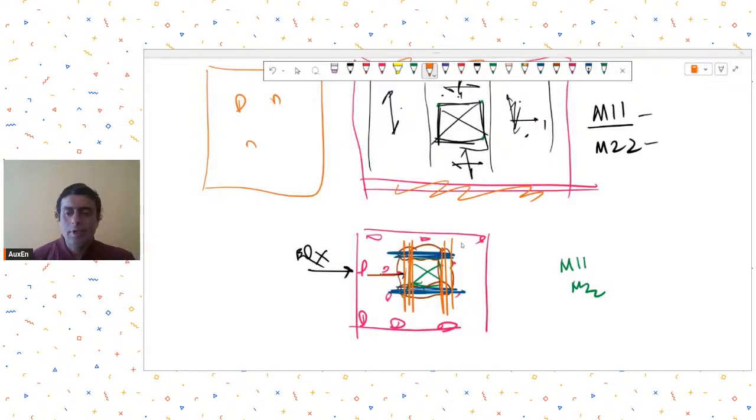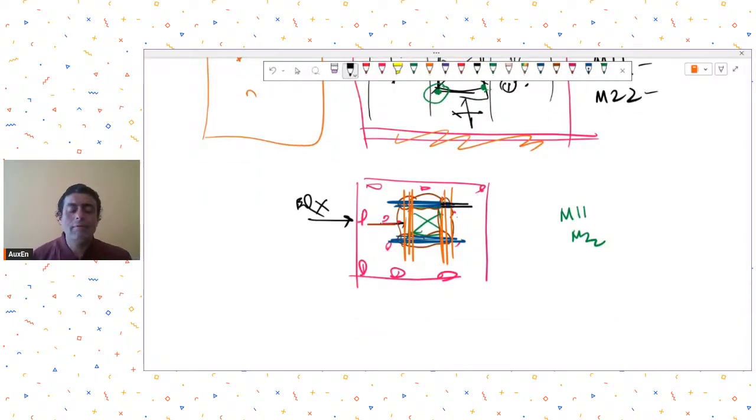So it can be a case of lateral loads or it can be a case of gravity loads. Then the third point is that around the openings at corners there is large stress distributions. So therefore, whatever reinforcement you have calculated for gravity load or lateral load, you need to not stop the reinforcement over here, but continue it till at least LD distance from the corner.